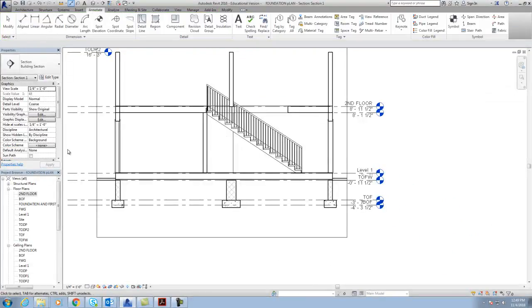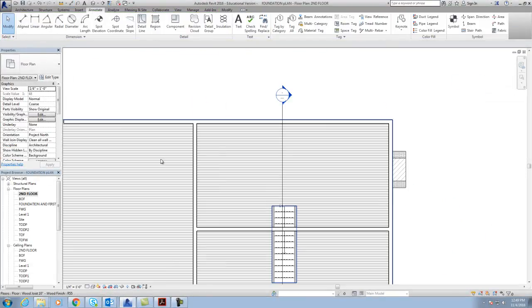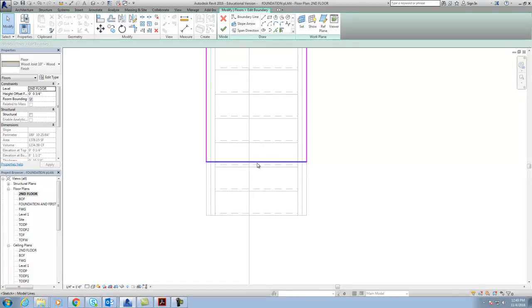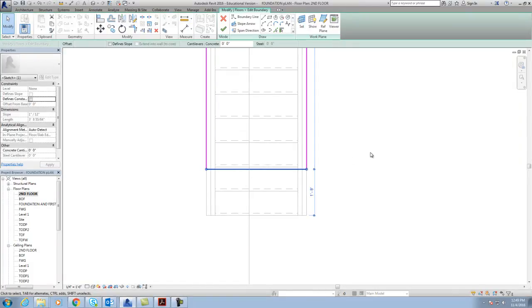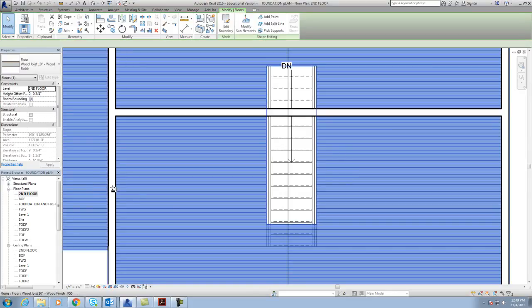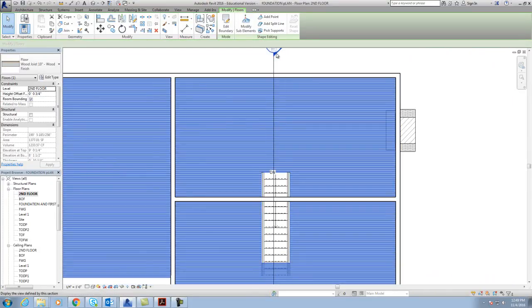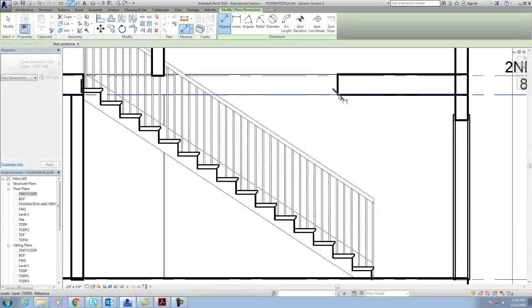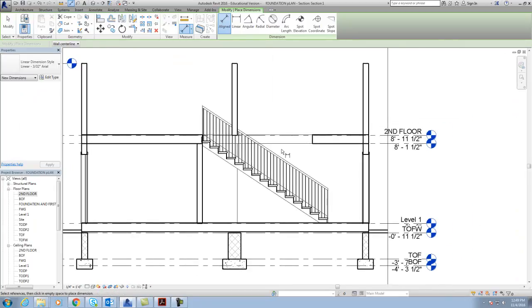Now, if you want to get yourself some more room, again, just go to your second floor. Make sure you clicked on that, edit, and then you can come down here, edit the floor, and then you can pull that just a fuzz more. Let's just make that 11.6, make it an easy number. Finish, and that gives you a little bit more room to walk up through there. And yeah, I think that might be even a little better. There's 6'5" right there, and then this one coming on down would be 7 foot. So that's plenty of room to get stuff up through there, no problem.